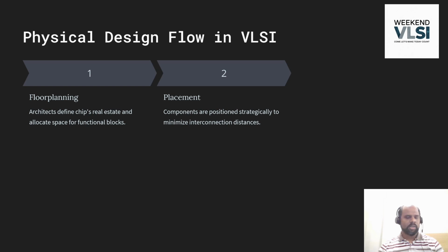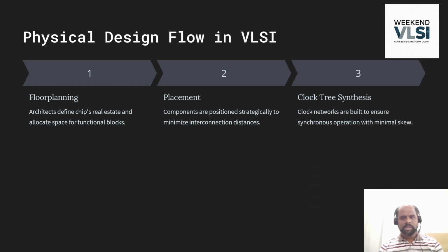Okay, and the next stage is clock tree synthesis. Okay, why do we do clock tree synthesis? Very simple. We need to clock all the registers and macros or memories, right? That is the reason we do clock tree synthesis. The clock source, right? We have defined the clock source in the block, right?